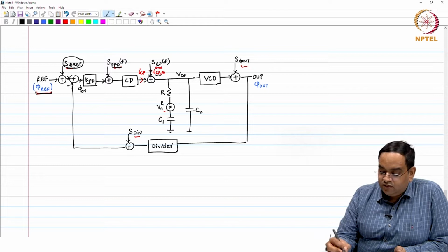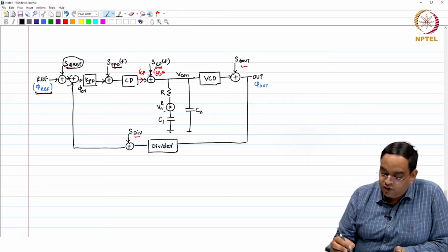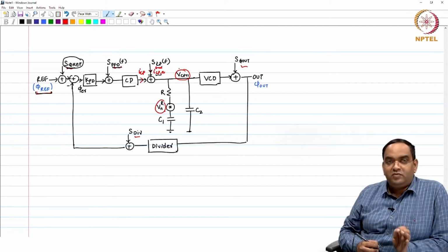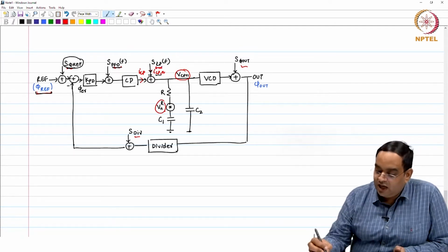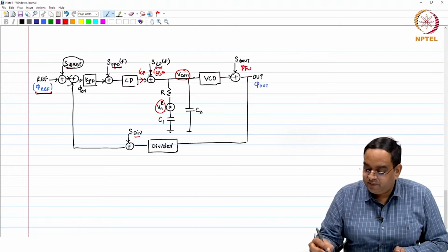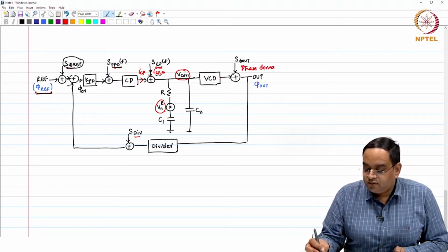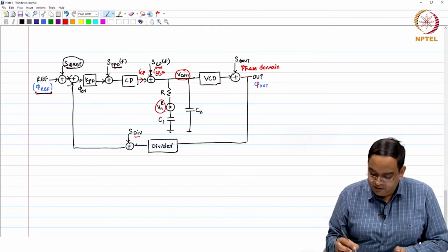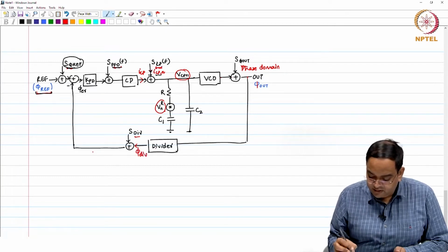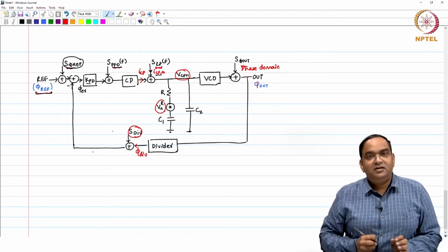This is what we control. So, your voltage noise here adds to the output noise, control voltage noise in voltage domain. The output phase, we are looking at the output phase. So, the noise from the VCO adds to the output phase in phase domain. And at the divider, the output of the divider is taken as phi divided, right. So, the noise from the divider acts in the phase domain.